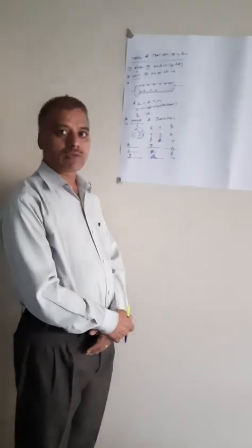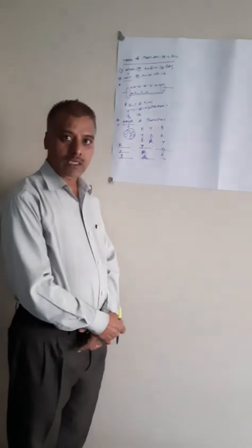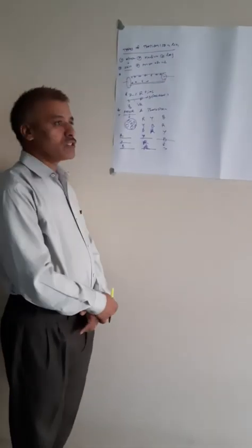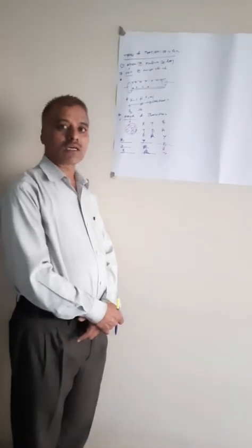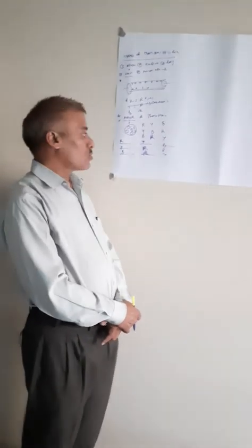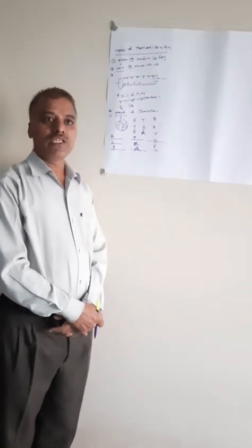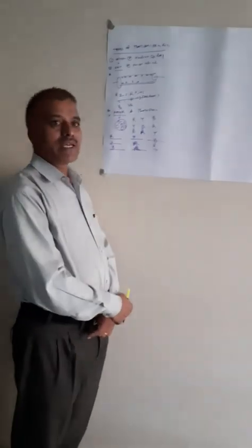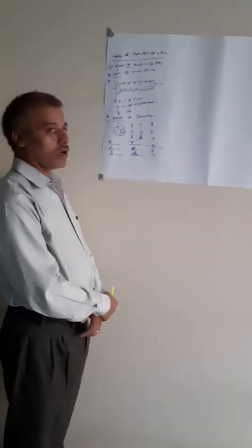The first conductor, combined with the second conductor, is also minimized. So transposition of the conductor means changing the position of the conductor after some kilometers. That type of positioning is called the transposition of the conductor. Generally, this transposition of the conductor is commonly useful to minimize the inductance in the transmission line, and it is commonly useful for long transmission lines.